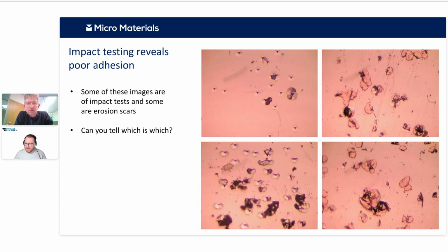Okay, let's move on to the next question from Sankara, who asks, impact is unidirectional, but the erosion occurs multidirectionally. How would the correlation work? Well, even if there's multidirectional erosion, there's a dominant gas stream and a dominant particle stream, so there's a dominant angle of attack that you simulate with any one test.